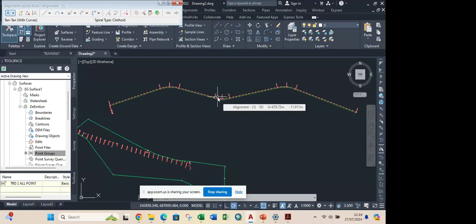From there, you have the leverage to play, edit, and shape your line and do all sorts of things with the alignment. So I don't normally recommend this automatic method for beginners. The method I adopt is not to use the line trace, but to take your line and go across the path, then get your alignment. I will display that method now on the screen.